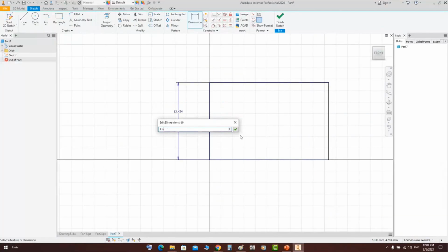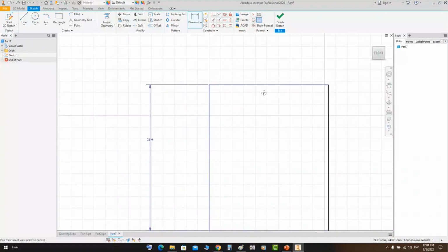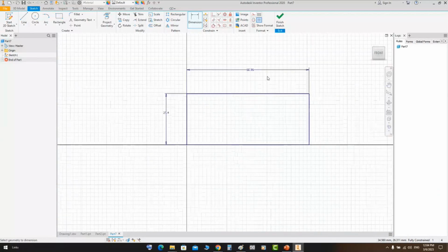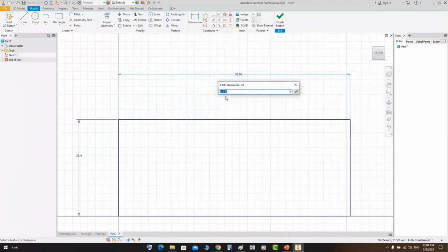After adding it in that format, 1 inch, and clicking yes, it will be converted automatically because the file's measurement unit is millimeter. So it will appear to you in millimeter, which is 25.4. But if you double click on it, you will find it in inches as you defined. Again, if you write it as 0.2 foot and press enter, it will be converted to millimeter because that is the default unit. But if you double click on it, you will find it in foot, like that.